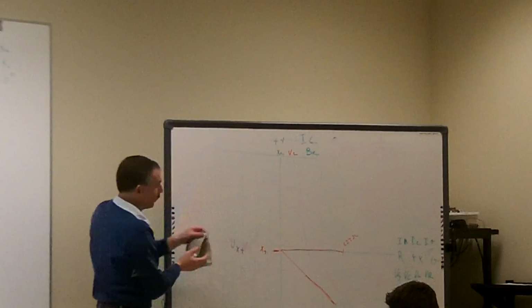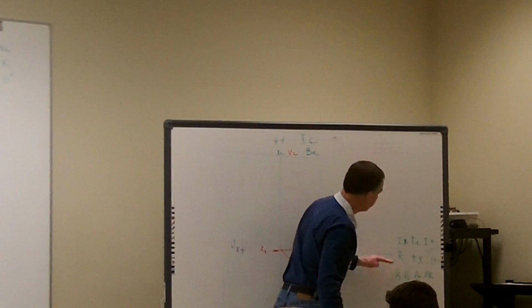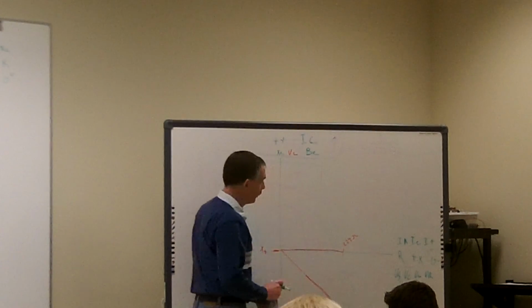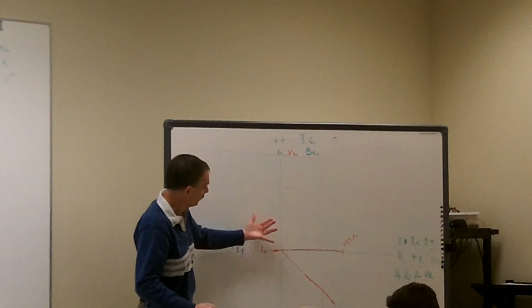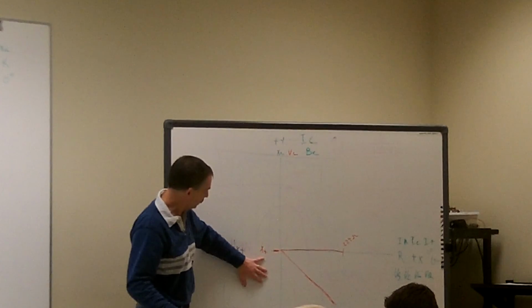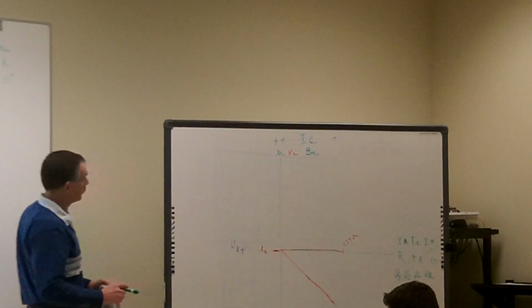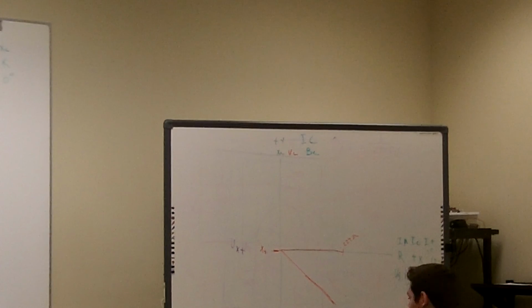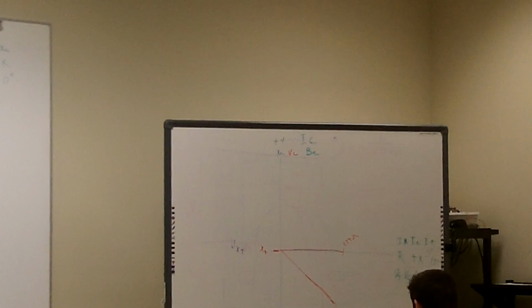So it's still the same way of handling it. We just have to remember what remains constant: in a parallel circuit, our voltage, so that's all at 0 degrees. In series circuits, it's our current. And then we just flip these around. Parallel, we're looking at the current for our vectors. Series, we're looking at our voltage. Otherwise, they get calculated basically the same way. There are some more advanced filters, and we can take a look at those tomorrow.